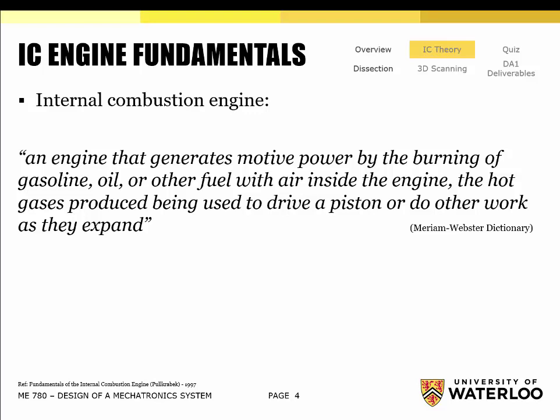The way it's defined here is an engine that generates motive power, motive meaning work, and dynamic power, by the burning of gasoline, oil, or any other fuel with air inside the engine. Okay? So we're excluding electrical devices from this because we're talking about a combustion process that's actually producing the work. And within those types of engines, there are 2 different categories: internal combustion engines and external combustion engines.